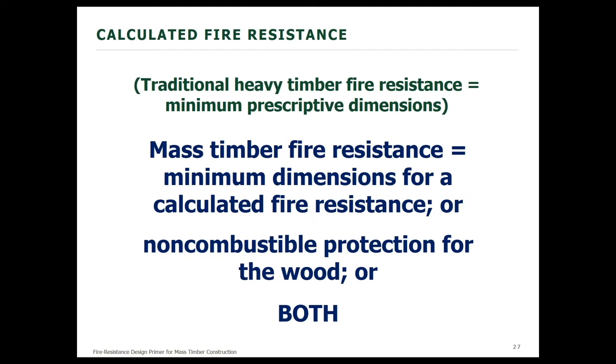So, as a summary, the fire resistance of traditional heavy timber is recognized solely by its minimum prescriptive dimensions. The fire resistance rating of mass timber is based on the calculated fire resistance of exposed wood. The fire resistance rating is based on its non-combustible covering, like gypsum wallboard, or it can be a combination of those first 1 and 2.